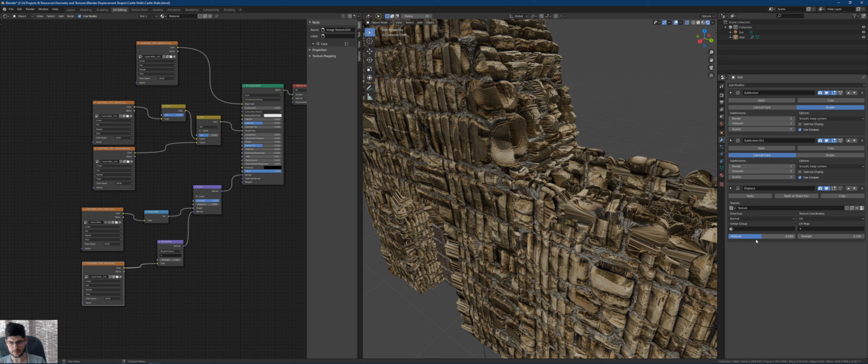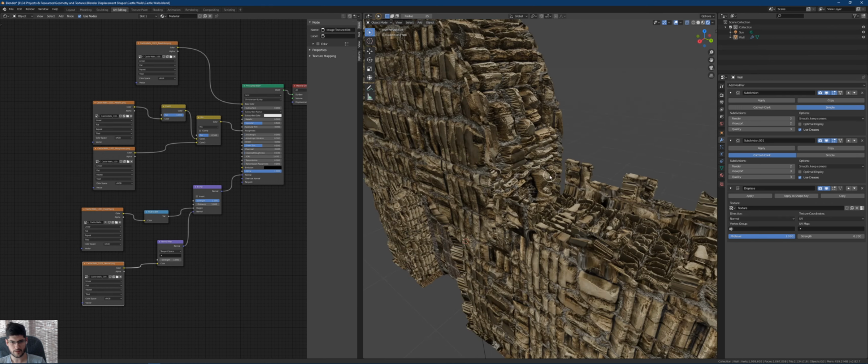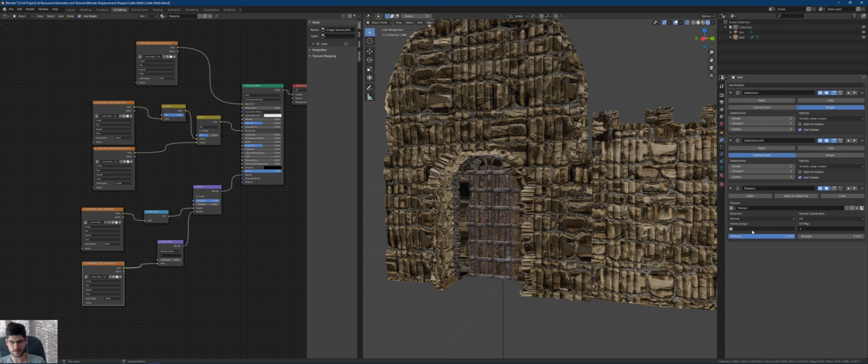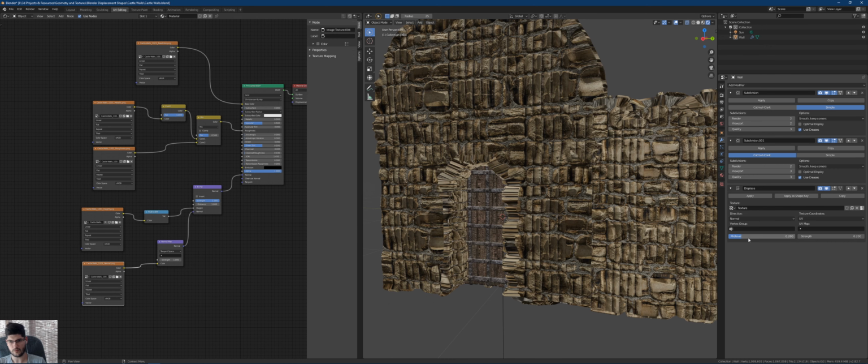I've made a mistake of sliding it, which then means that it's going to freeze my application just because we got too many polygons into play. So playing with the mid-level basically will reduce that, but actually I thought it was the other way around. If you make it smaller, it should make it better. I've just switched it now to 0.2 and see what sort of effect that has. No, obviously it means that if you do the mid-level higher, it will make the mesh look worse. So we're just going to take the mid-level over to 1.